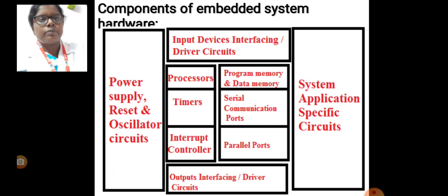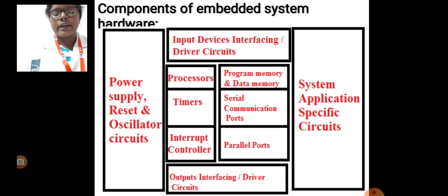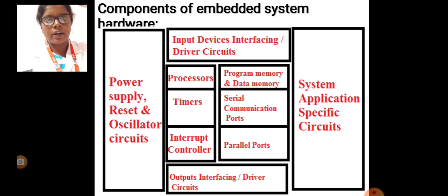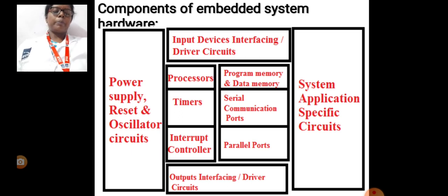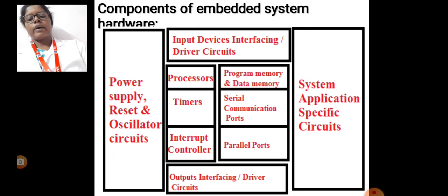We can see multiple parts in a microcontroller chip. First one is the functional circuits in the chip, which contain a processor, external memory interface, interrupt controller, data and stack in internal RAM, input output ports, UART communication port, serial port, timer, and watchdog timer. Okay, the application specific circuits are DMA controller, AD converter, LAN controller, network driver stack, modem, printer controller, and DTMF controller. These are all the applications of a microcontroller.